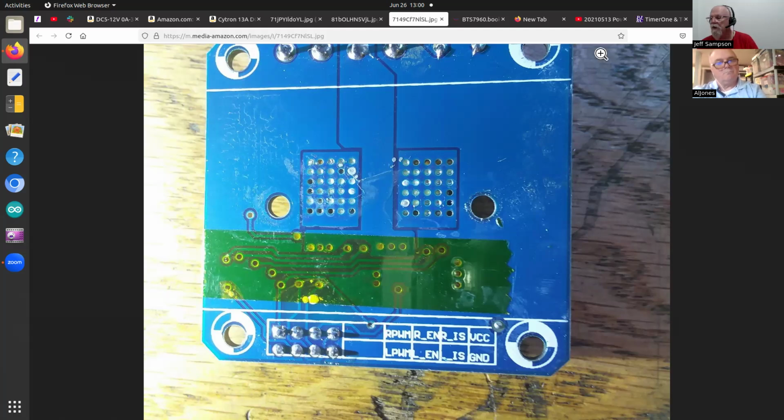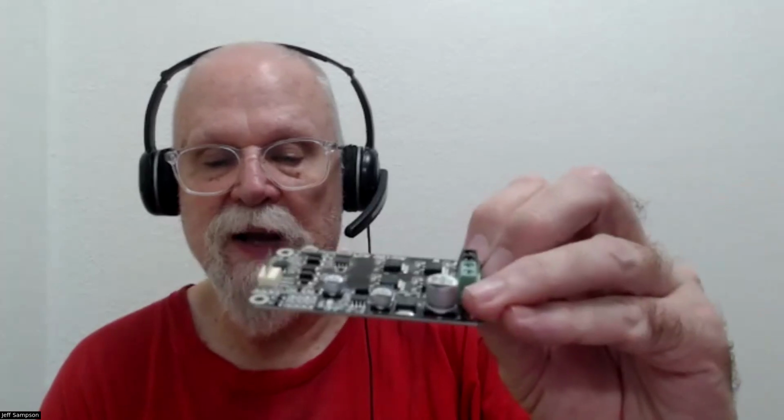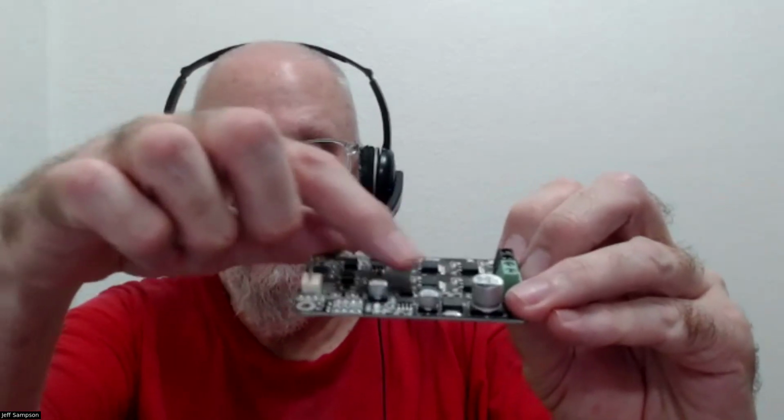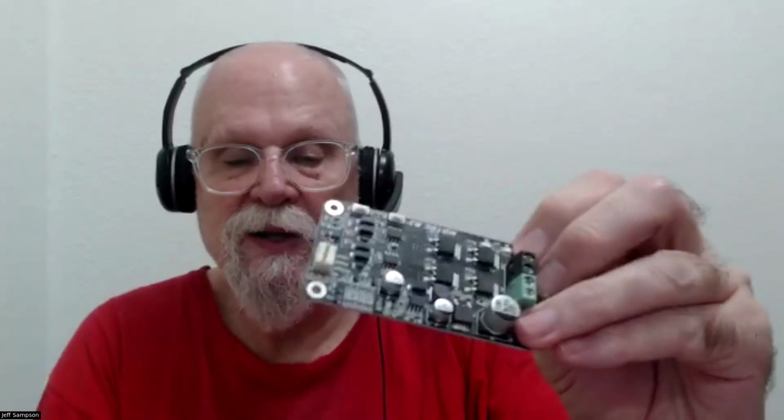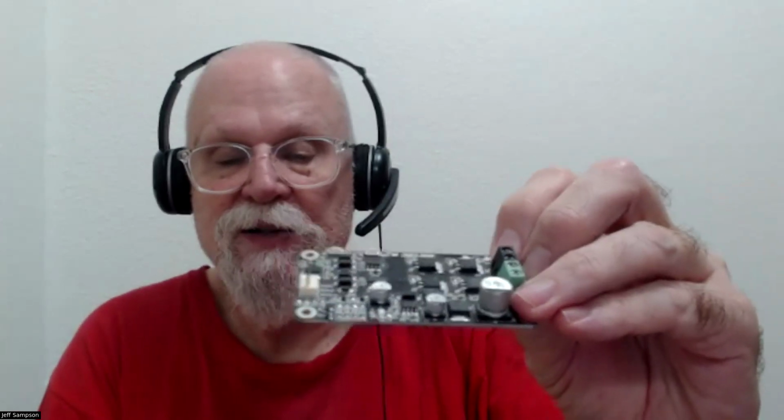And other boards, this happens to be one of those Cytron boards, and it's just got bare MOSFETs on there, and they claim you can run 10 amps continuous through this board. It's just the modern MOSFETs are much better, and they don't dissipate as much heat. And I've got other, well, we can go back to this.